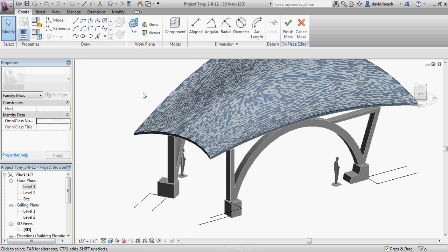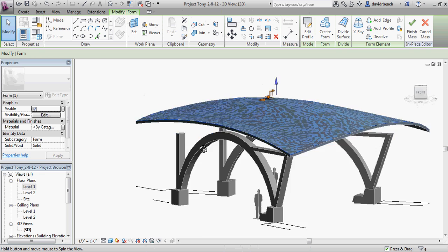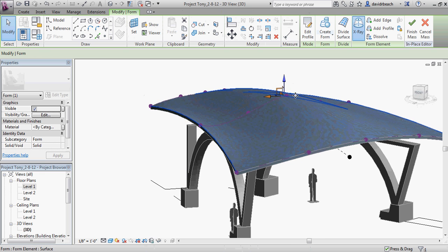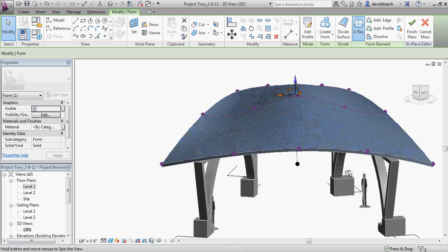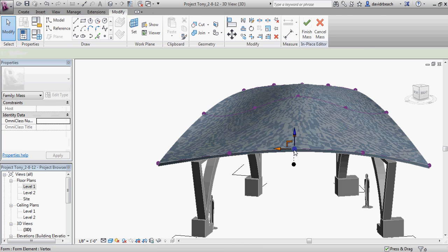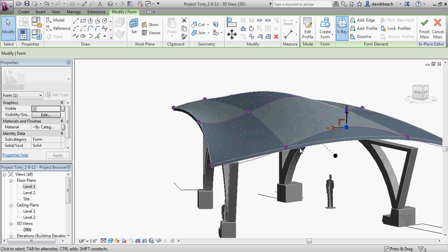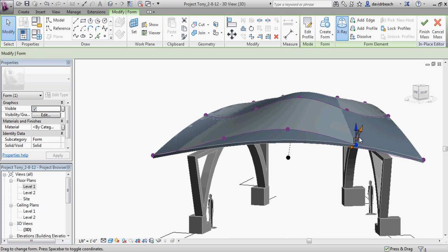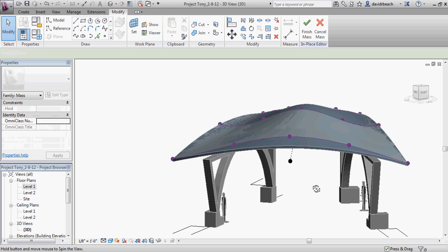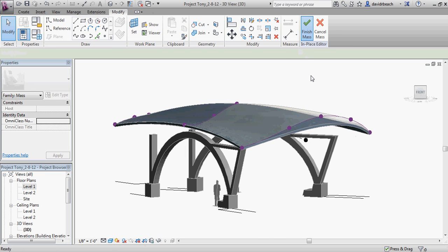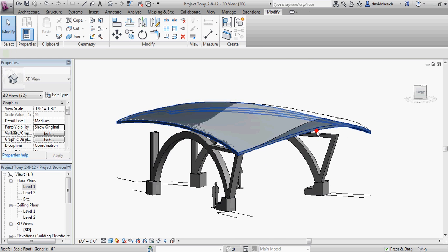And let's edit in place. And that should get me down to my massing model. So if I come back and say X-ray, if I make a change to this, let's say I want this arch in the front to be more prominent. I begin to pull that and this piece up. If you'll notice first, this roof is not following that. Okay? So if I say finish mass, it is still not following that.